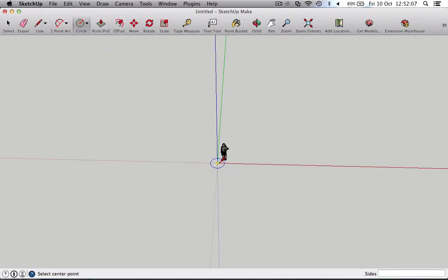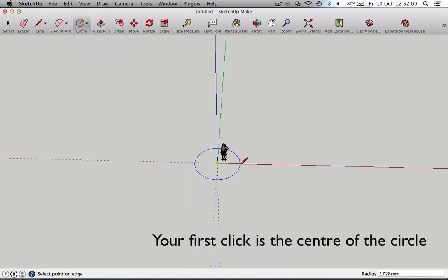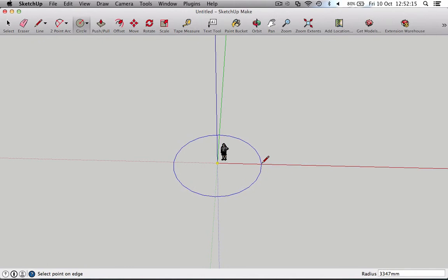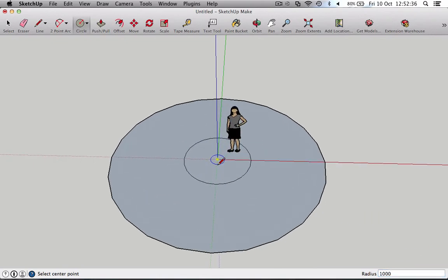Clear the workspace up. Working from origin again. And this time, instead of saying dimensions, it says radius, which means the distance between the pencil and the origin is currently 3.2 meters. Now, if we wanted to create a circle that had exactly 1 meter in radius, we do what we did with the rectangle, except we don't put a comma, because there's only one dimension we're using.